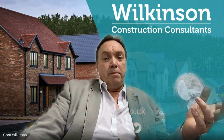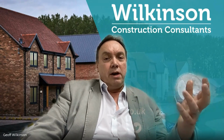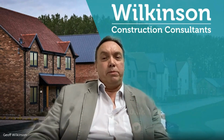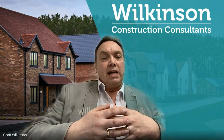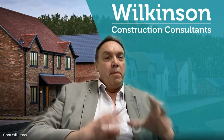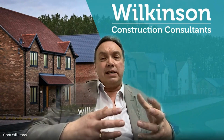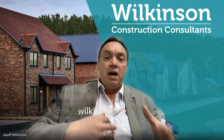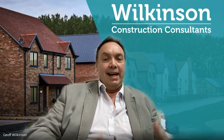Some of the things that you can do, what's known first of all as a desktop study. Now, a desktop study involves looking at the available geological and environmental information that you may have about the site. So you're looking at things like what was the site used for previously? Was it a petrol station, for example? Was it a car wrecking yard? What's gone on this site in the past? Because that may give you an understanding of some of the risks that you'll be detailing against.